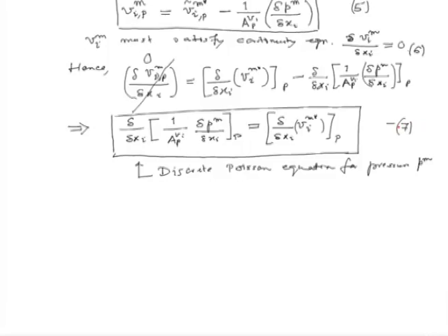Let us call this equation 7. So, now let us have a look at the summary of the equations which we have got. We had the linearized momentum equation 2, which was for the intermediate velocity field Vi m star. So, we can solve that equation using values of the velocity at the previous iteration and the pressure at the previous iteration. So, Vi m star is known.